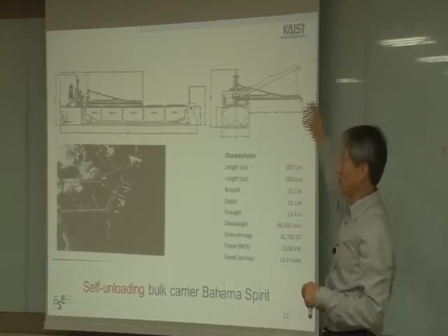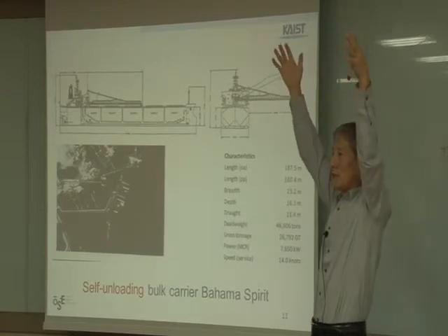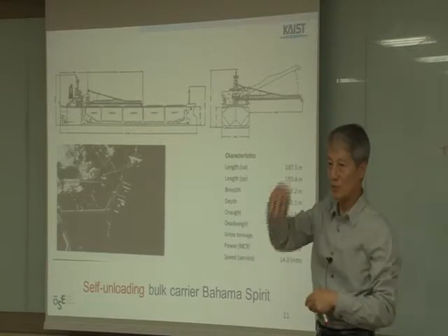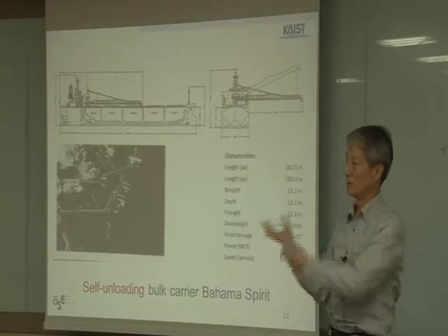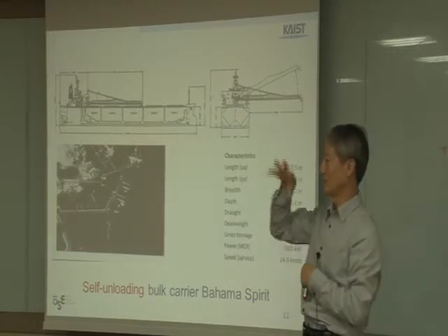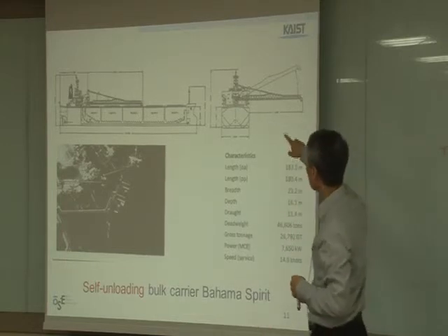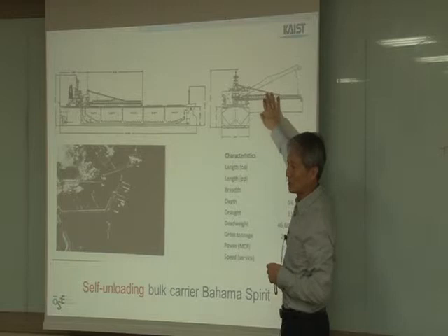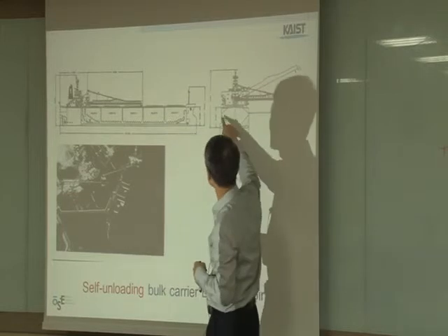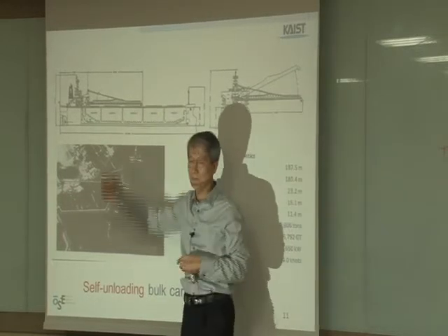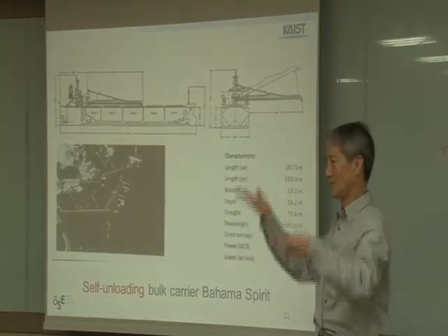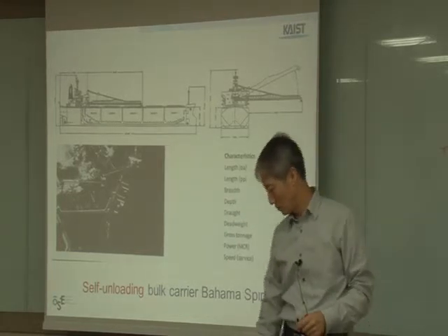Loading from the port is okay because a silo is a big tank. They have grain and pour it down into the ship very fast, similar to water, but it's grain pouring down. But unloading is very complicated. Grabbing is very slow, but self-unloading is very nice, faster. But you can lose space there because of the shape. Also, the cargo gear equipment has a power and money cost. So depending on your situation, you can choose.